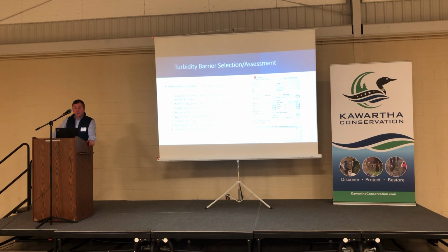Particle size, we talked about that already. And then what type of anchorage are we looking at? And what does that bottom consist of? Is it hard rock or shale, where it's going to have a difficult time securing anchorage, or is it a clay, silty material where an anchor will hold quite well?